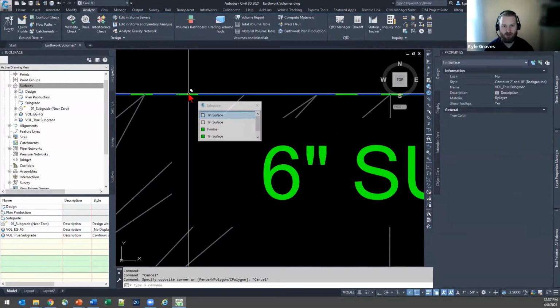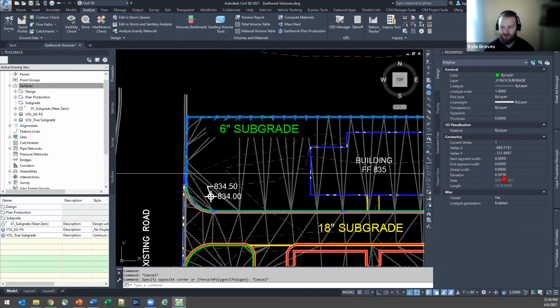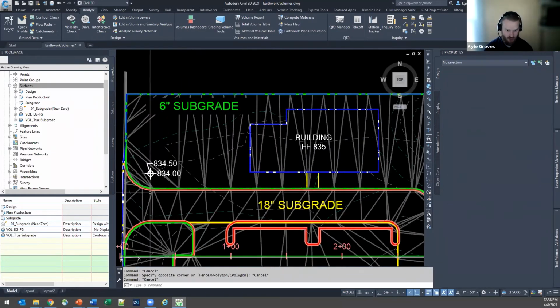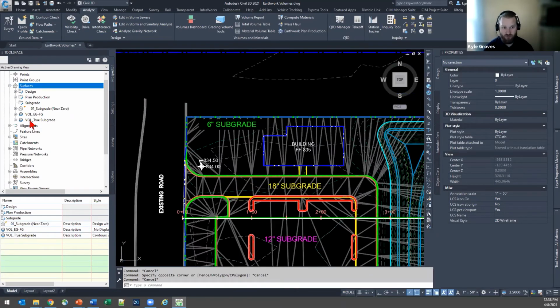Sorry, I tried to grab that polyline. I'm supposed to be 0.5 feet underneath, and I've got that positive elevation assigned. So this is working correctly, and this is why we check. But that's how it's supposed to go. And that's why we also have the positive elevations assigned with all of these boundaries in our geometry. So that's cool. And this volume surface, this works.